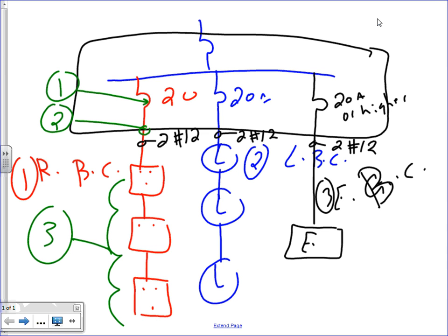The best way of working in a 3-phase system, the best way to do your branch circuits in a 3-phase system is to move in 3-phase. For example, I have a receptacle here. So I'm going to go, this is from phase A. This is going to be 3 circuit breakers, 20 amp each. Cool? 3 circuit breakers, 20 amp each.